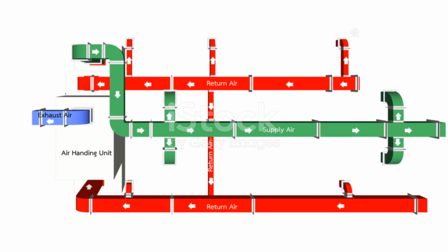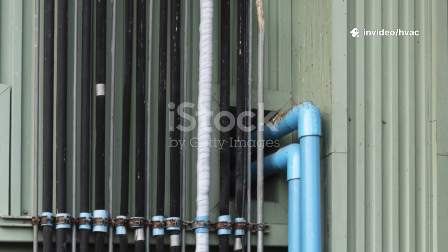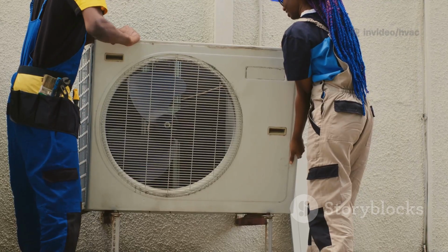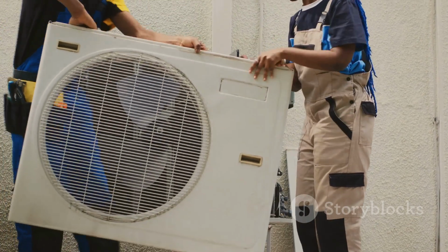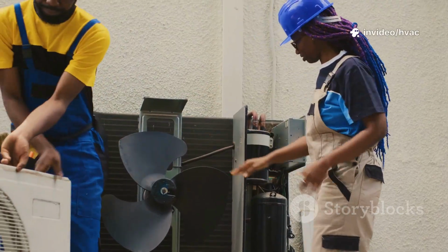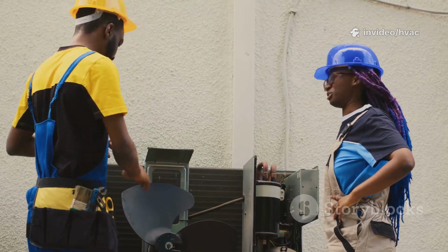Worked example: if your duct is 3 feet high and 8 feet wide, plug those into the formula. Area = 3 feet x 8 feet = 24 square feet. This is a typical size for a large supply duct. Step 3. Use the industry rule of thumb: 1 linear foot of sensor for every square foot of duct area. Formula: sensor length (ft) = duct area (sq ft). This ensures the sensor samples air across the whole duct.